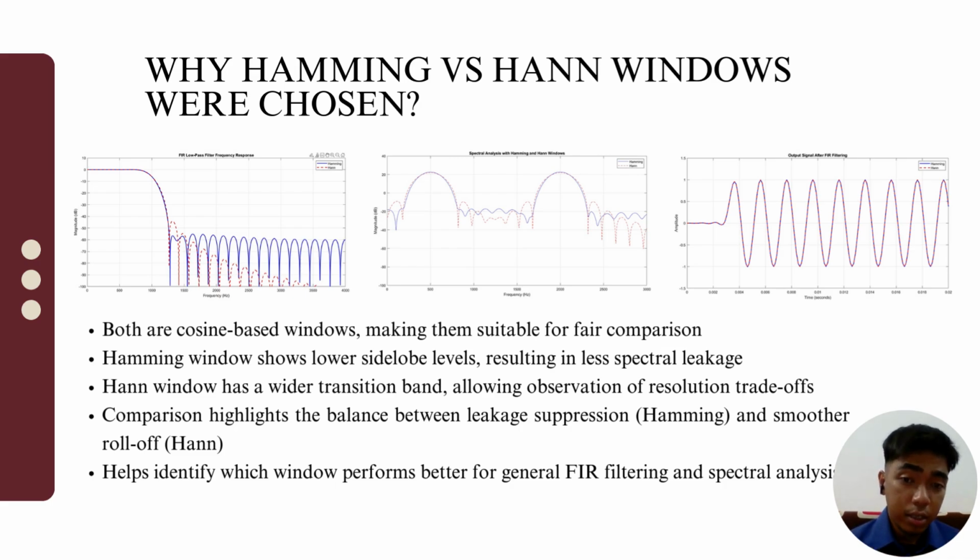In this plot, you can see the main lobe of the window. Both windows accurately identify the signal peak. However, notice the width of the main lobe and the height of the side lobe. The Hamming window provides a slightly flatter slope, while the Hann window is smooth at the edge. The comparison matters when detecting a weak signal in the presence of strong noise.